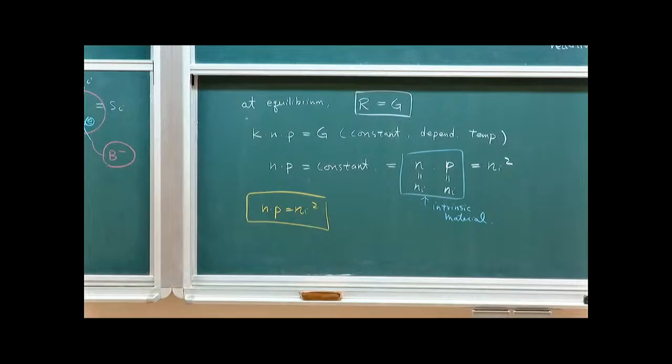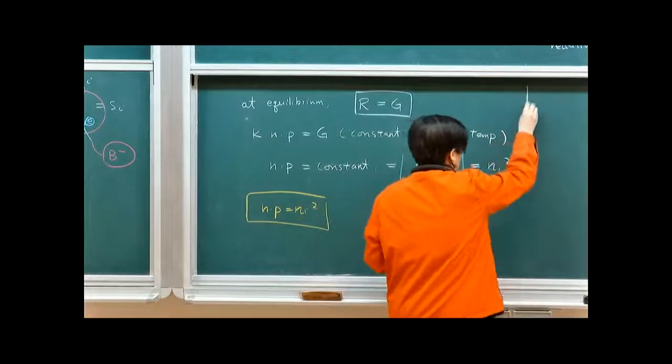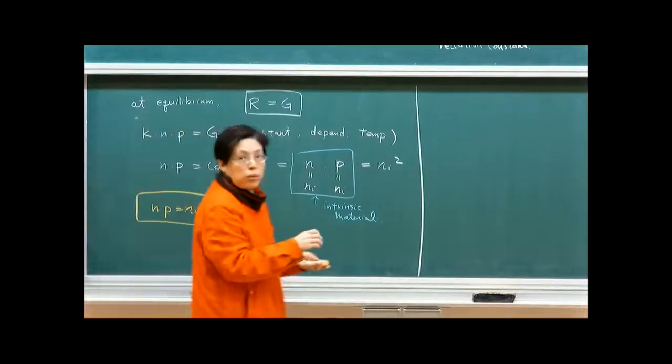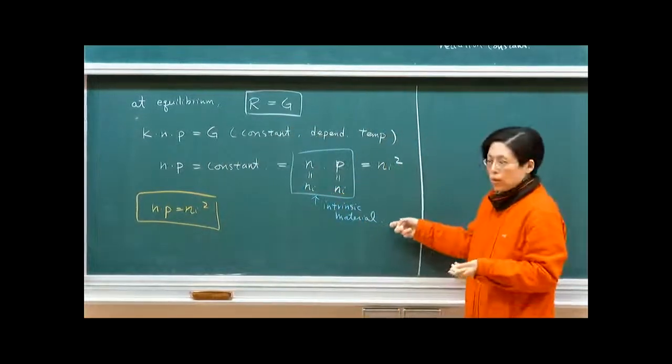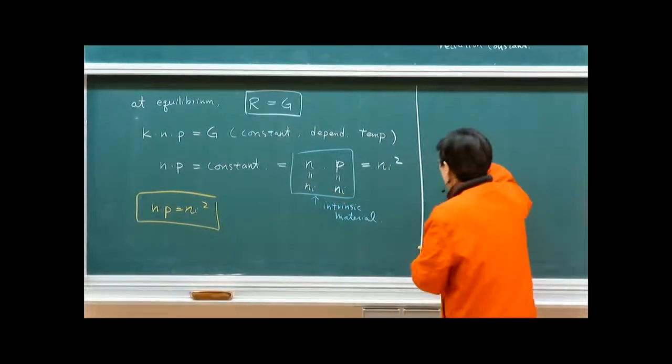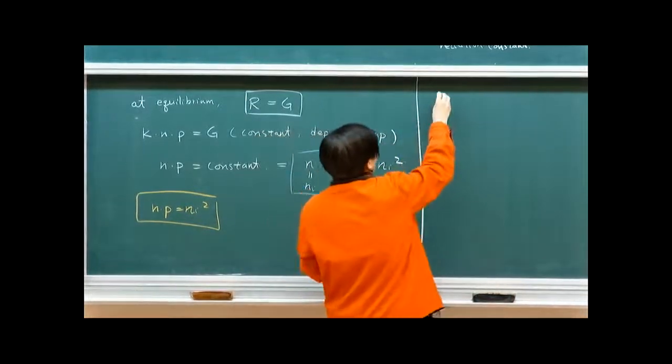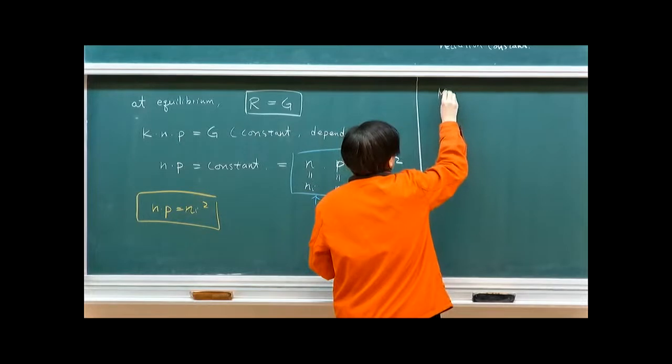And because of this law, we can follow up on finding out, once again, that the charge neutrality equation allows us to find the majority carrier, and your minority carrier concentration is then determined by the mass action law. So we go back to the 10 minutes, right? 10 minutes, mass action law. Okay, so let's think about how you find minority carriers.